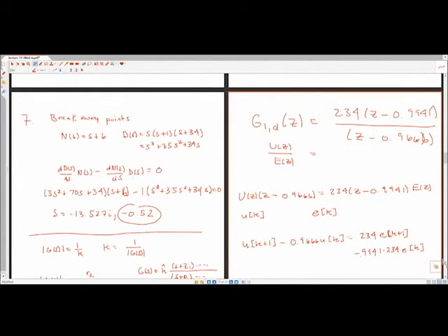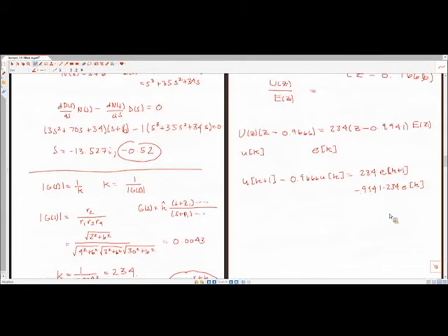So somewhere in your computer, the next time step that you're going to send out of your data acquisition system is going to be equal to my previous time step, if I move this over to the right-hand side, plus my current error signal minus my previous error signal times some sort of gain.